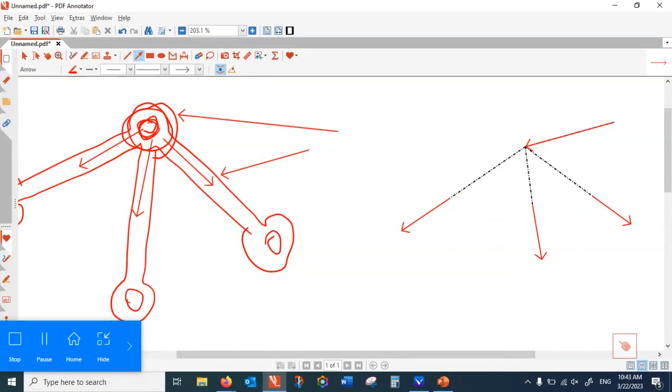Because if you start with another joint, then you find some forces. Those forces are shared. Whatever I find in this member, that is the very same force that applies to the second one, right? So once I solve this joint, the very same result I can transfer to the next node when I'm applying the method of joint to that. You notice what I say?